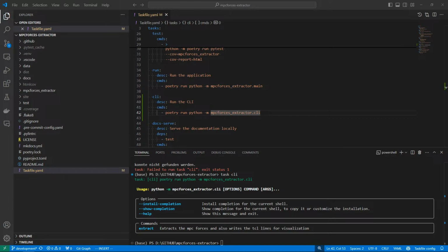And if you have a part and you describe the first 10 higher moments of this part, and you can compare that, those 10 higher moments will be the same whether you have that part rotated or not, moved or not. It will be the same. It's like an invariant property of the part. Something like the stress tensor, right? It doesn't make any difference if you're just pushing the element to the side, turning it. The stress tensor and its invariance will be the same.